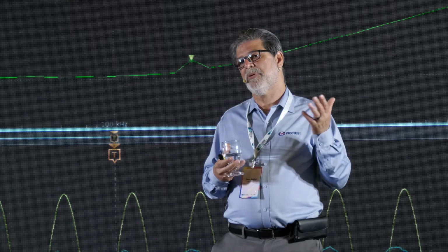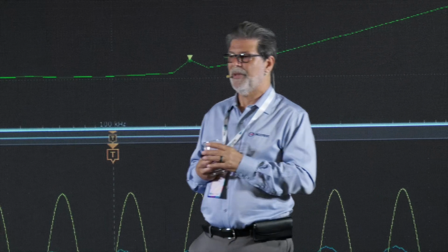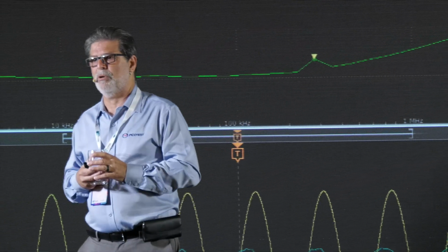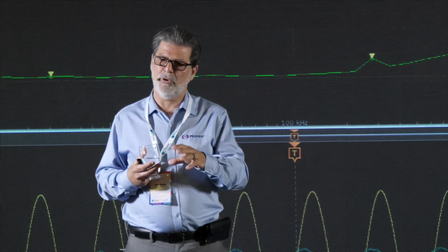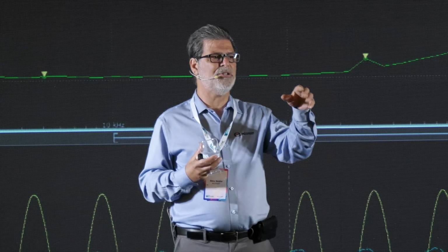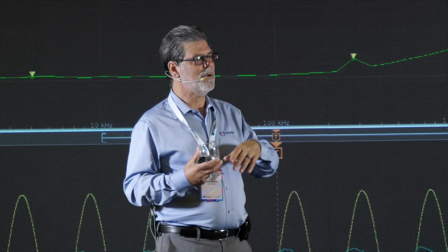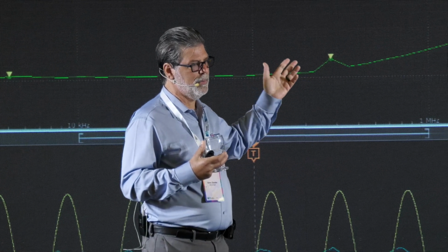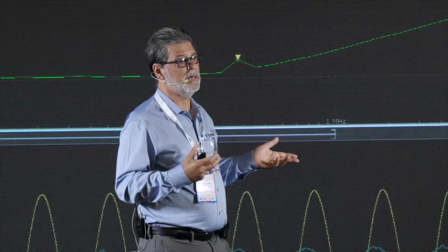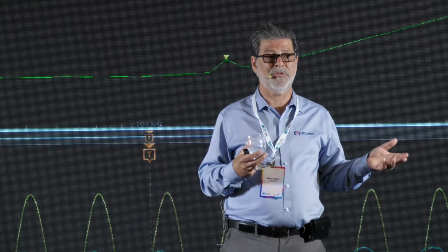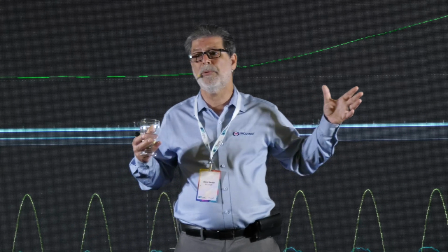So I would say that you've got to be really careful. The numbers are all relative. In a low power circuit, you could have ohms of impedance, and at 2,000 amps, it might be 12 microohms of impedance. It just really matters what the total voltage noise limit is. And that's why I'm saying that you can't just use a resistor network, because the resistor network says, okay, we're going to take all of the other noise sources and just ignore them. And then we're going to do a calculation based only on dynamic currents, and then you're going to start to have problems because of all those other noise sources that you ignored. We need to consider this as one big ecosystem.